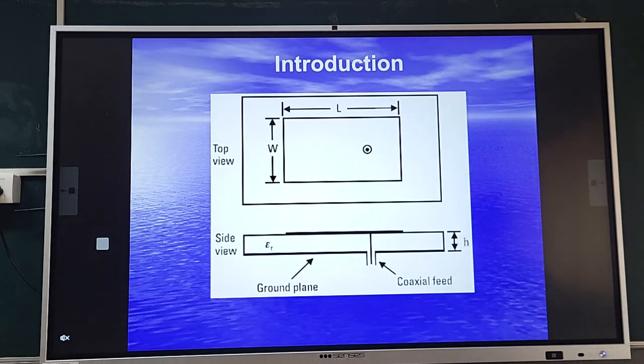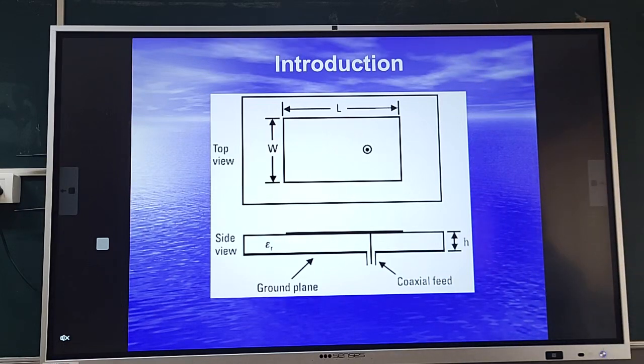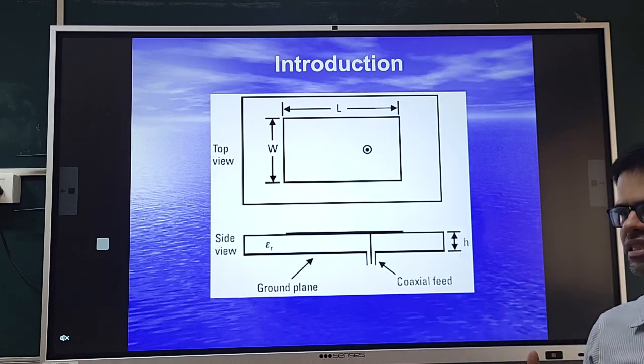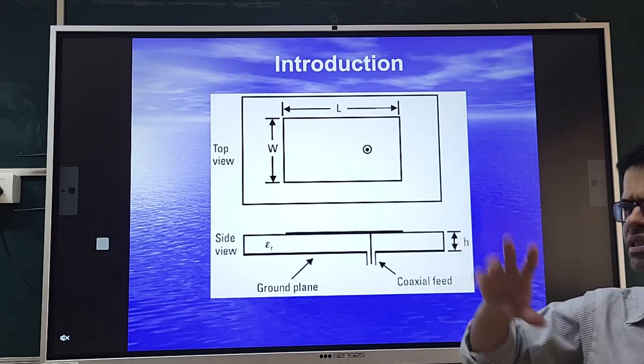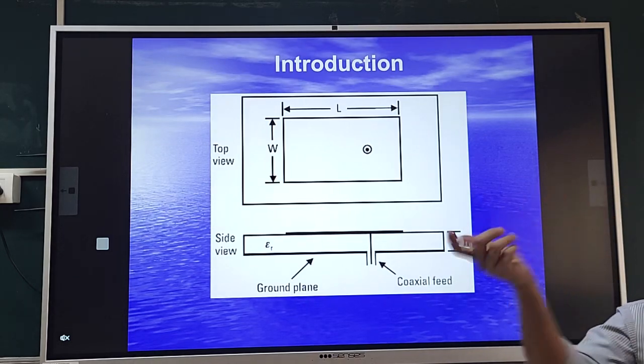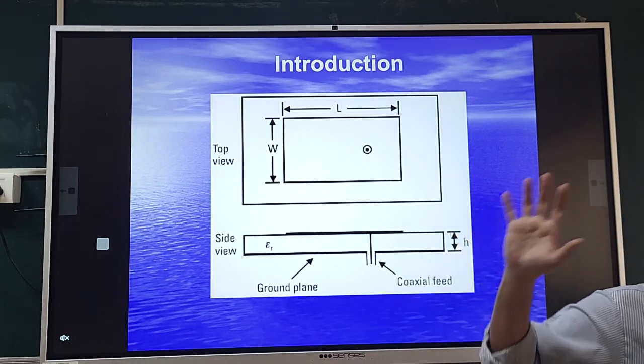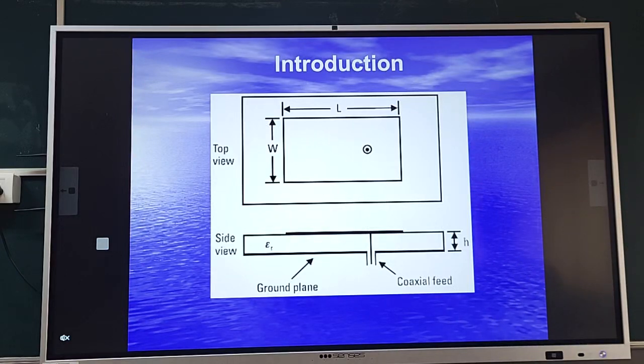But I want to remove, or reduce, that charge storing ability. Then only will that charge be leaked out into free space. For that, in a microstrip antenna, I generally use a lower dielectric constant substrate. Earlier, when I discussed the substrates, I mentioned a few whose values are less than 5. Another substrate used in microstrip line designs is the alumina substrate, where the dielectric constant is 9.8, but we do not use this substrate for the microstrip antenna design.